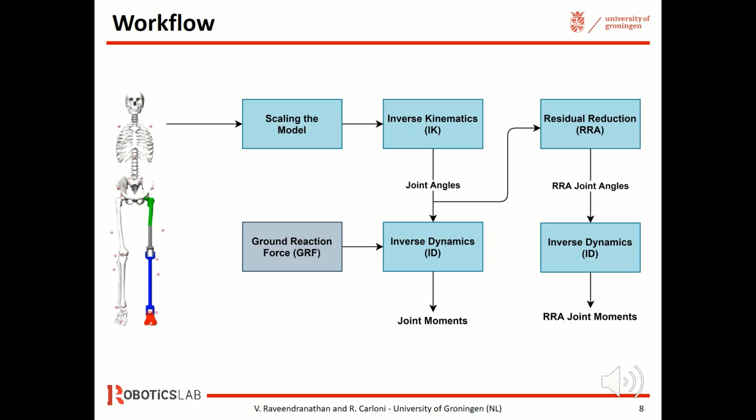After scaling the model, we performed the inverse kinematics tool in OpenSim to compute the joint angles, and with the kinetic information and the joint angles, we performed inverse dynamics to compute the joint moments.